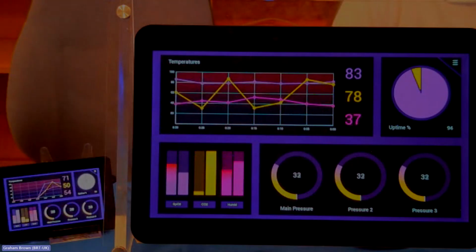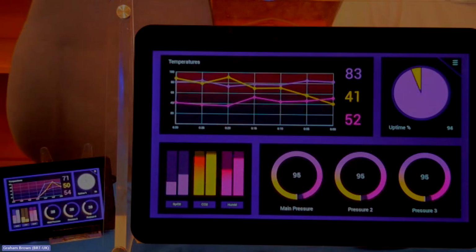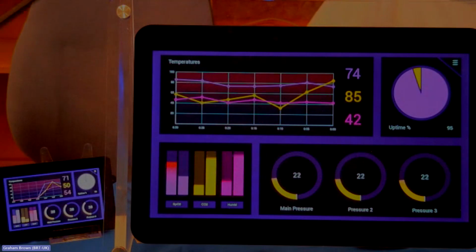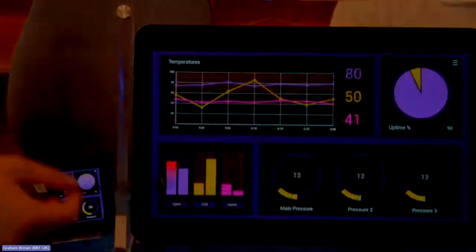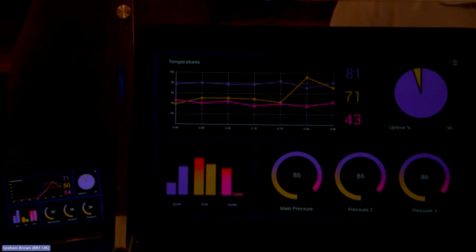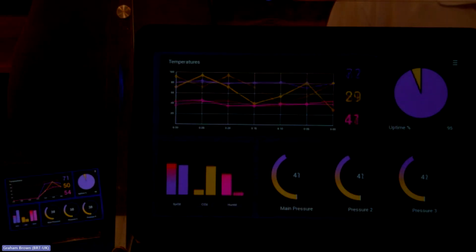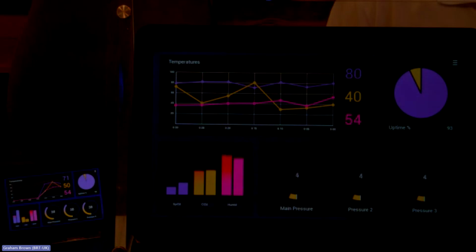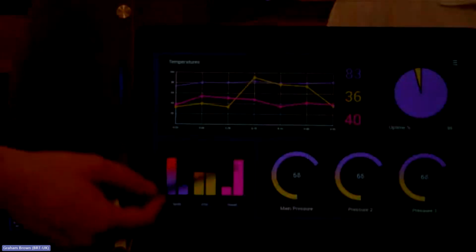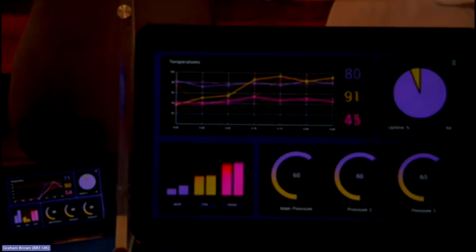So one of the main benefits of Eve that Graham has already mentioned is that it offloads all of the graphics processing from your MCU. So this data visualizer example was generated by issuing SPI commands from your MCU to Eve. And this allows us to generate shapes using graphics primitives, such as circles or lines or rectangles on the screen, and offloads all the computation required to do that from your MCU.